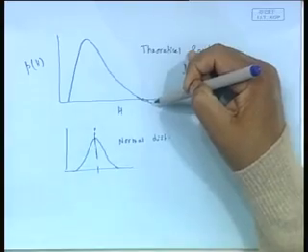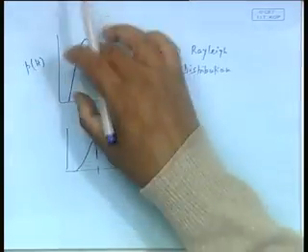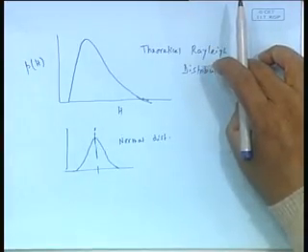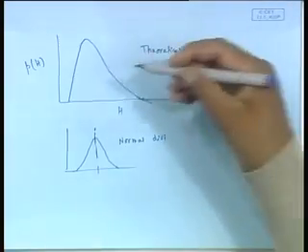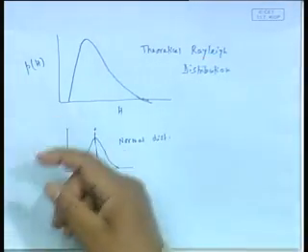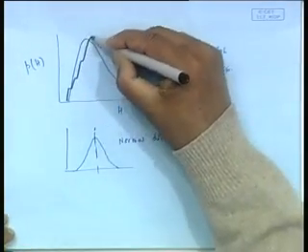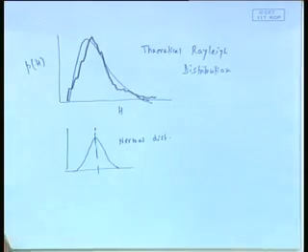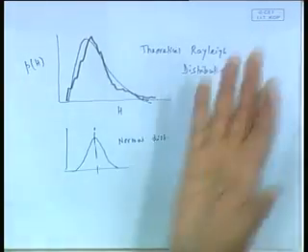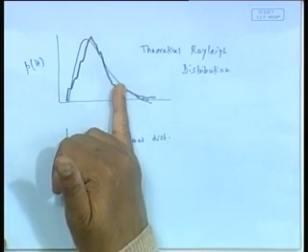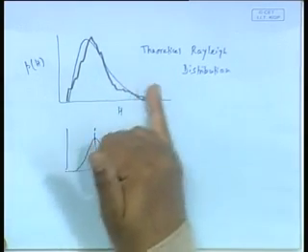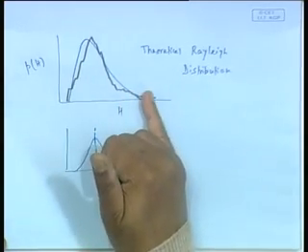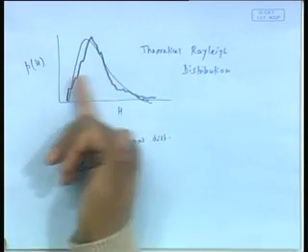But here it turns out to be Rayleigh, which is biased, slightly hanging on this side. You may ask whether it is exactly this or not. Well, actually, if you fit the graph, some data might look like that, another will look like that, but it resembles closely the theoretical Rayleigh distribution. There is a very interesting physical reason you can think of why it is so. You see, what it means is that the chances of higher waves occurring are actually lower, but lower wave occurrence is always higher.